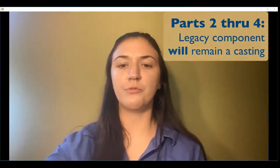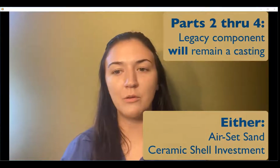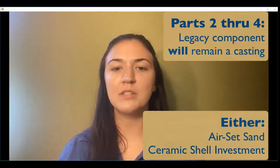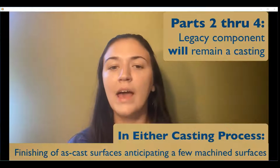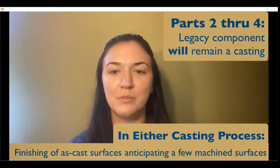In parts 2 through 4, we acknowledge that the legacy replacement part will remain a casting, and we will walk through the two most powerful metal casting processes for high specification legacy castings. That is, the air-set sand and ceramic shell investment casting processes, and in either mold process case, how to plan for the finishing processes on the as-cast geometry prior to machining a few surfaces to final net shape. Since so much of a casting's final net shape remains as cast, finishing processes on those surfaces is important.